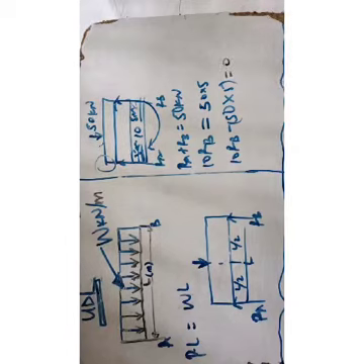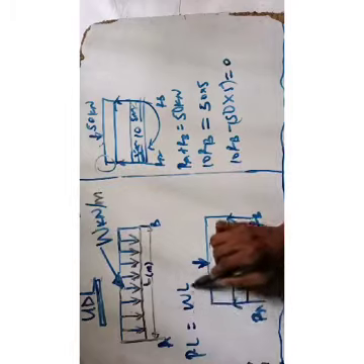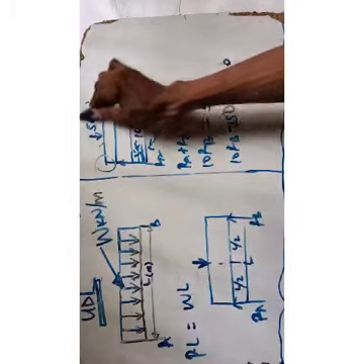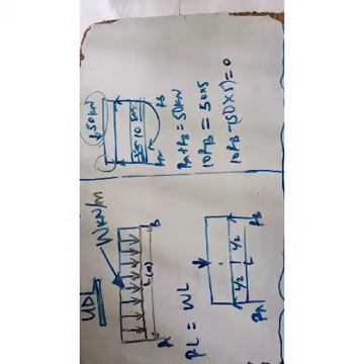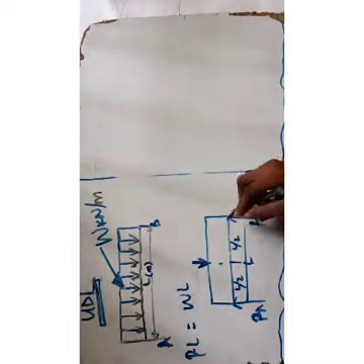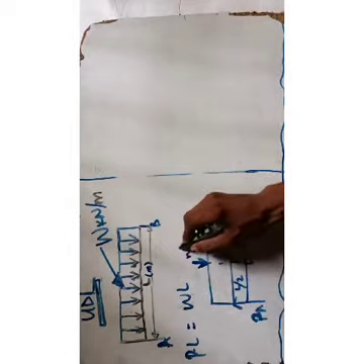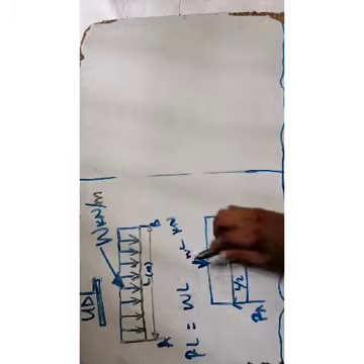Okay, so in another way, the same thing applies to this as well. When you have the point load to be WL, that is length times breadth, you convert this to an ordinary point load, like 50 kilonewton. You see, this does not have meter, okay? So when you have the ordinary point load, now WL is in ordinary kilonewton, so you can do your normal multiplication.